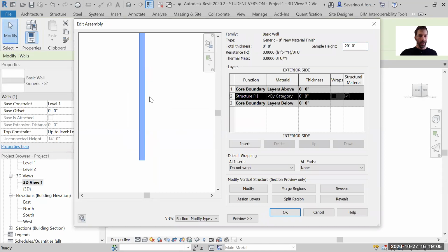As you can see in this particular wall that I selected, there's only one layer, and it is a generic. By the way, generic walls are normally assigned as a placeholder, and then you should rename them and properly create the layers. Generic is something that doesn't belong in a final project, because you should know better what's going on in your project than just generic.